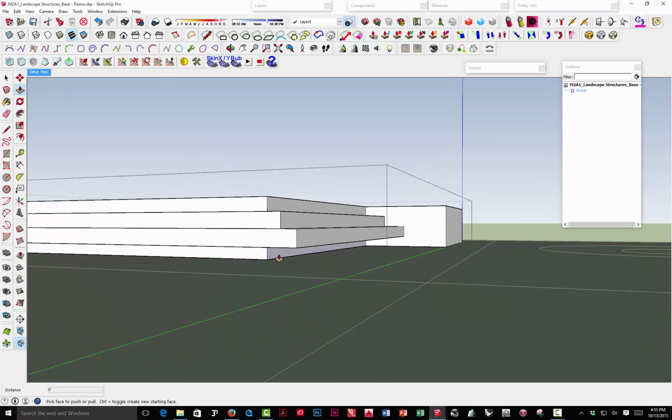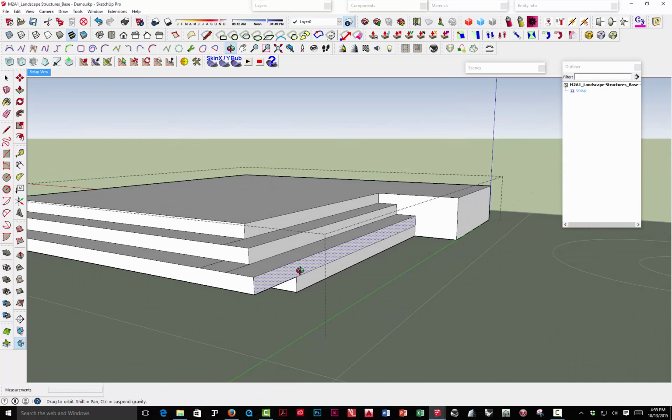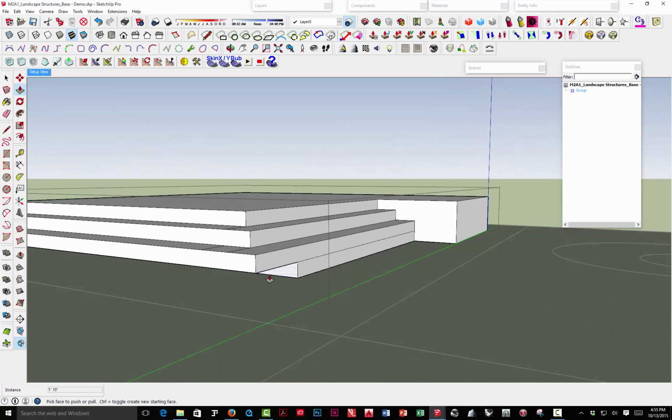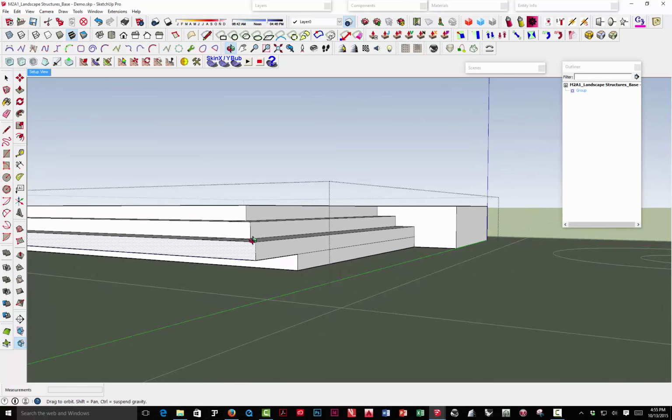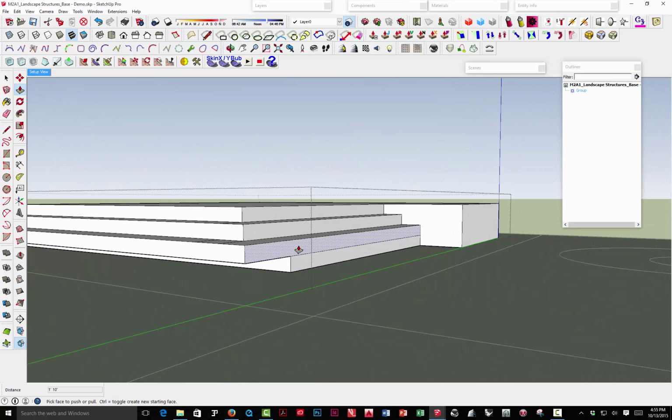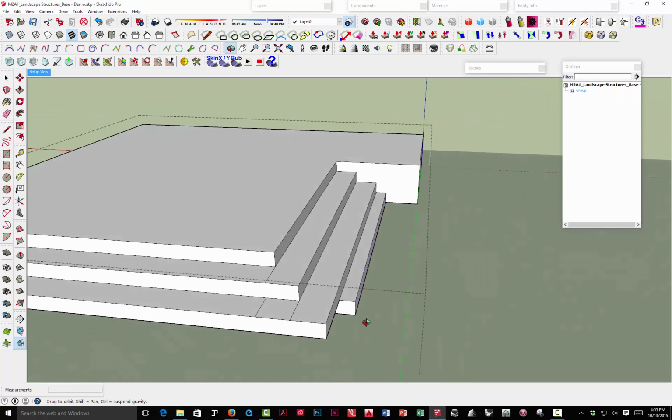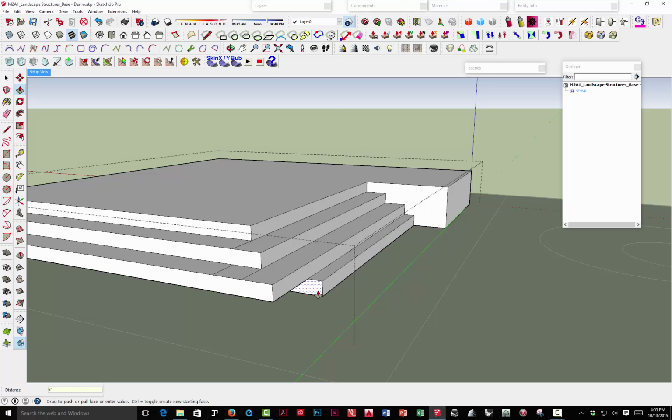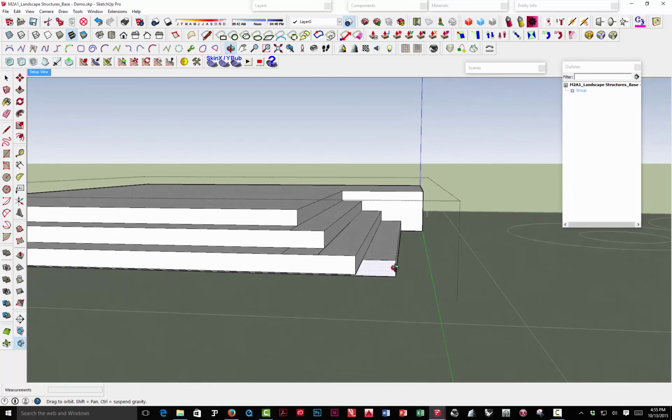Now here I'll do this 2 different ways. I can double click. Oopsies. Double click. Well, I messed that up, so now I have to fix it this way. Because I moved that a slight increment, I can't use the double click. So what I would do is what I was going to show on the other side. What I would do is just pull it out and snap it to here, then pull it out, 6, enter, and you've got that. And actually I need that a foot, so another 6, enter, and I've got 1 foot.